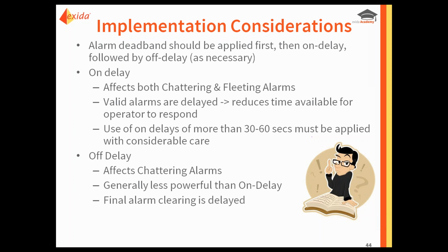Now, when it comes to use of on delay, that deals with chattering and fleeting alarms, but you have to be careful because you are delaying the enunciation of the alarm to the operator.